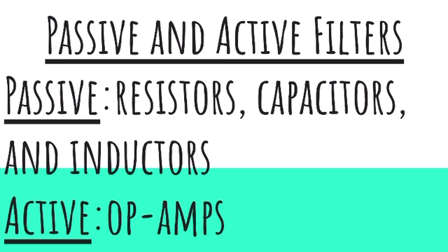Coming to the active filters, these are capable of dealing with very low frequencies, approaching 0 Hz, and they can provide voltage gain also. Active filters can be used to design high order filters without the use of inductors. This is most important because inductors are problematic in the context of integrated circuit manufacturing techniques. However, active filters are less suitable for high frequency applications because of amplifier bandwidth limitations. So, radio frequency circuits must often utilize only passive filters.